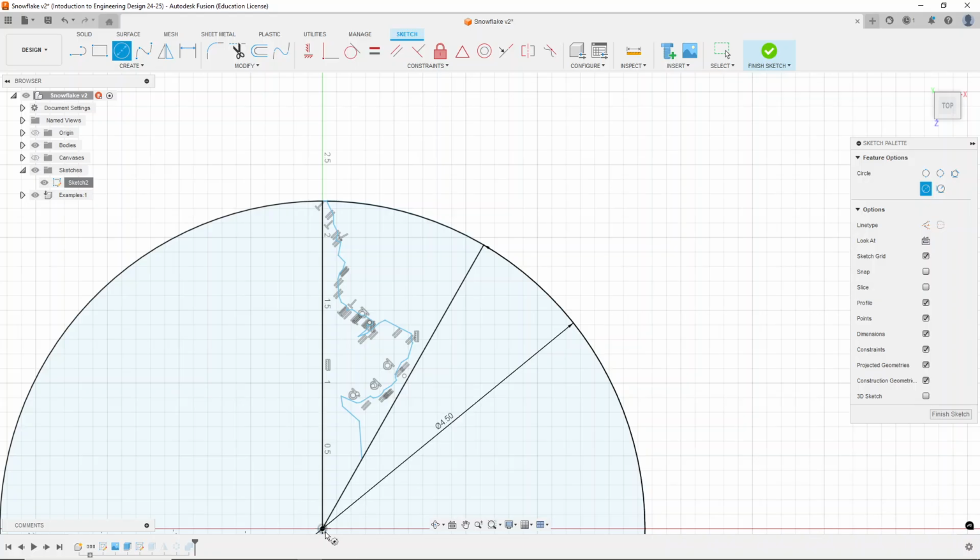And we're also going to create another circle, maybe at 4.25 inches. If we put it at 4.25 as the diameter, that means the difference between 4.25 and 4.5 will be our thickness of this outer rim. Since that's 0.25 inches, that's 1/8 of an inch on either side, giving us a ring around the outside. So if you want that, great.